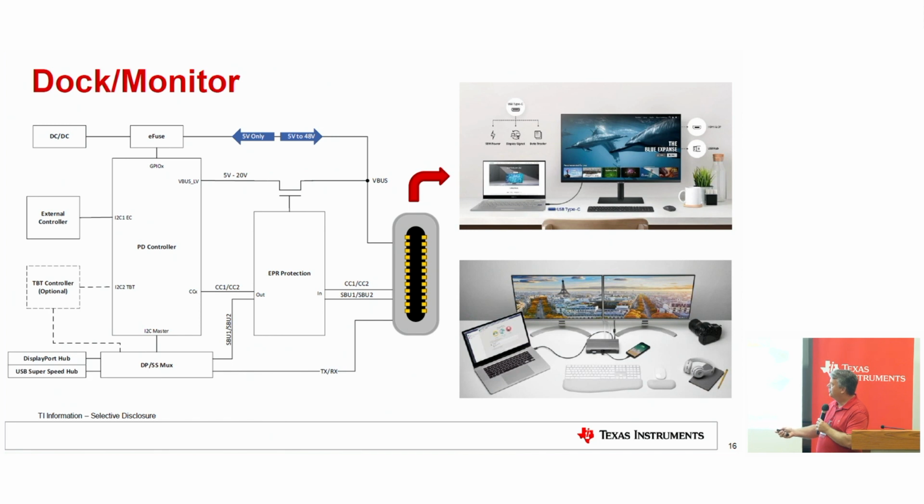I don't show the connections here, but between the DC to DC converter on the last slide, this slide, and the next slides, and the PD controller, we actually control and talk to the DC converter or the charger for what is the optimal voltage. After we know what contract we want to establish, we enable that through the DC to DC converter. Once that voltage is at its safe value, there's a negotiation process where we send power good, basically PS ready, power supply ready. That happens through I2C communication between the two.